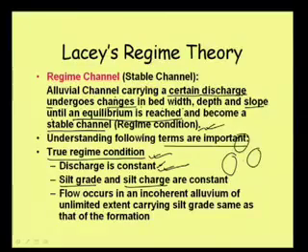Say these are bigger size and these are some smaller size. The smaller size will go inside and then the interlocking will be better. But if it is poorly graded, that is, uniformly graded, all of the same size, then there will be a lot of gaps in between, and that is why these are called poorly graded. And well graded means there is a mix of smaller and bigger, different sizes.